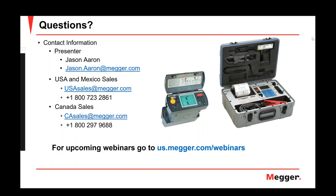There are also standards for the proper installation of these batteries, 484, 485. We'll talk about lead acid, vented and valve regulated. The worst enemy of a battery is temperature. So temperature is the worst aspect that you can have, increased temperature in a battery environment.